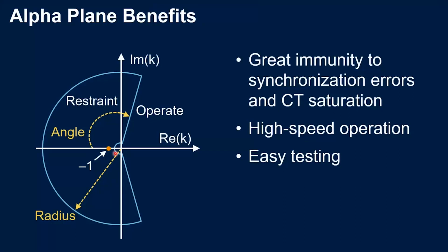And this provides, for the person that is testing and analyzing the differential element, something that is easier to test, because in this case we can manipulate, with the regular test set, the angles and the magnitudes of the currents we are injecting, which are directly reflected on the alpha plane.